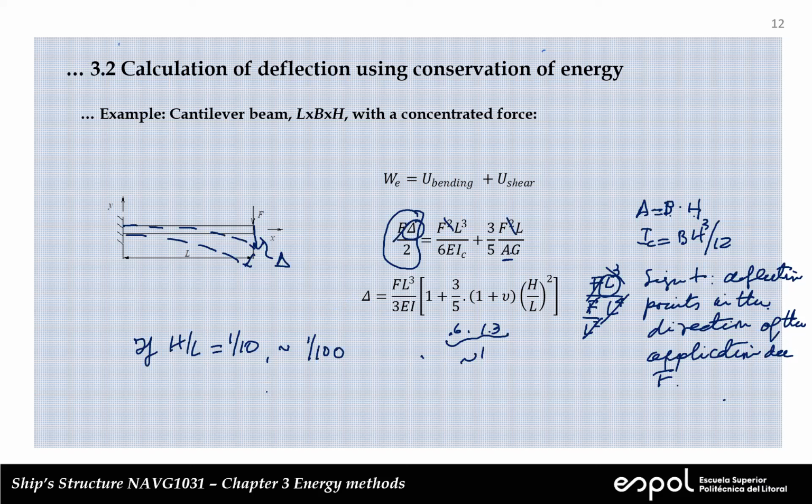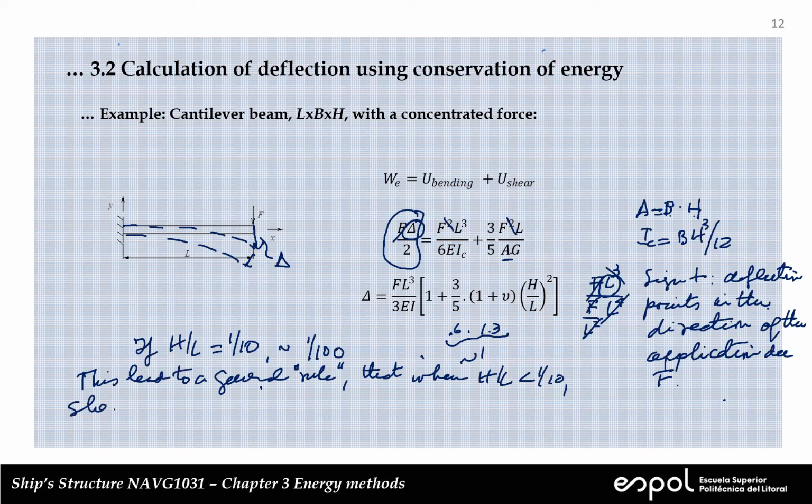I'm going to write it here. So this led to a general rule that when h over L is less than 1/10, shear effects are small and neglectable.